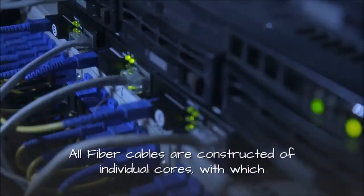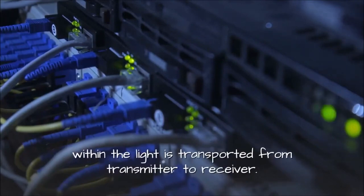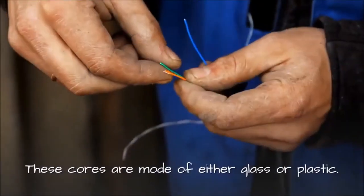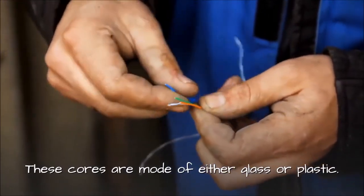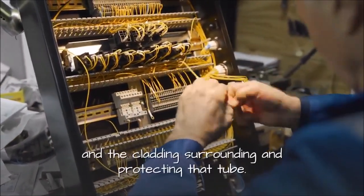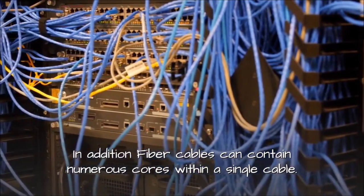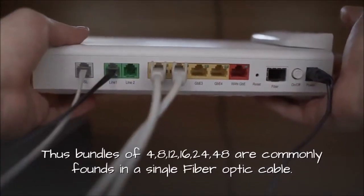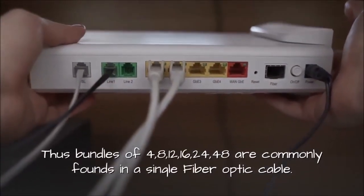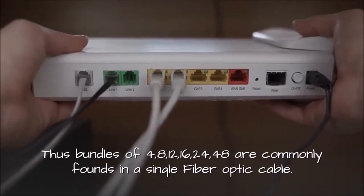All fiber cables are constructed of individual cores, within which the light is transported from transmitter to receiver. These cores are made of either glass or plastic. Furthermore, they consist of the actual inner core and the cladding surrounding and protecting that tube. In addition, fiber cables can contain numerous cores within a single cable. Thus bundles of 4, 8, 12, 16, 24, 48 are commonly found in a single fiber optic cable.